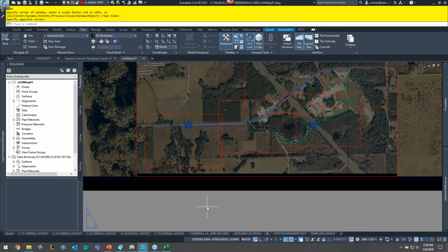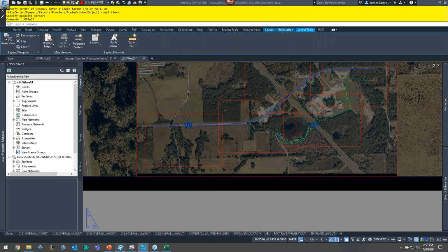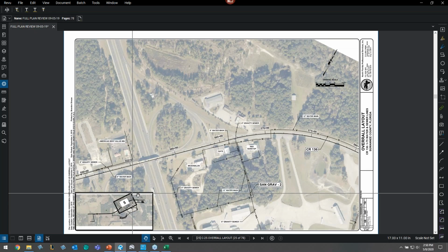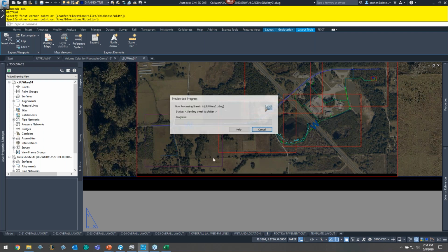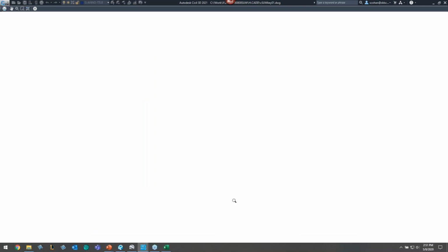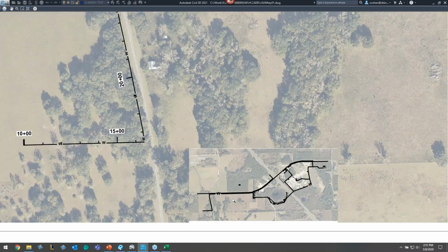Now, what I want to do though, as I mentioned here, is have an area that shows hatching, so the contractor knows exactly where this is. Well, guess what? The reason I drew those rectangles on a no plot layer is I can now actually do it in here. Let me change my layer to a plottable layer. And now I will just draw a rectangle. I'm in paper space now, so this is not going in model space. I'm going to snap to those spots. And now if I do a print preview real quickly, I now have an area that will actually plot. And if I want that thicker, I could change the line weight or the color, whatever I want that to be. That's fine. In this case, we'll just go with it.